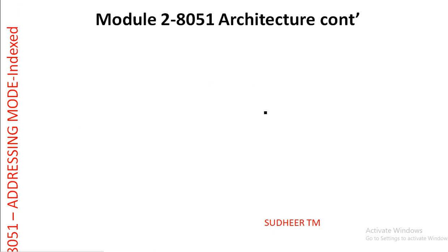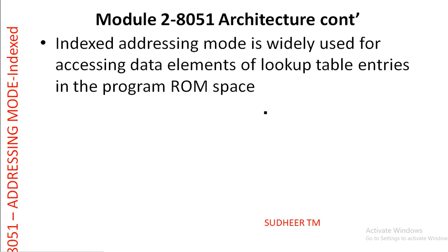Then the next addressing mode, indexed. The last one is the indexed addressing mode. Indexed addressing mode is widely used for accessing data elements of lookup table entries in the program ROM space. This is an important concept. There is a concept called a lookup table.